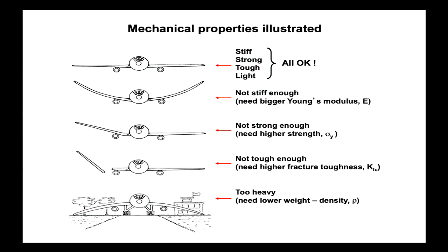Just since I've brought it up a couple of times, I don't know how many of you people eat bags of chips or bags of lollies, those plastic bags that, if you pinch and tear across the serration, it's very easy to create a crack that propagates. If, however, with that same material, try and do a tensile test. Now, everyone's done that, I hope, with an Instron machine. Grab either end and try and pull it apart where there is no discontinuity and see how high, if you like, the ultimate tensile strength is going to be.